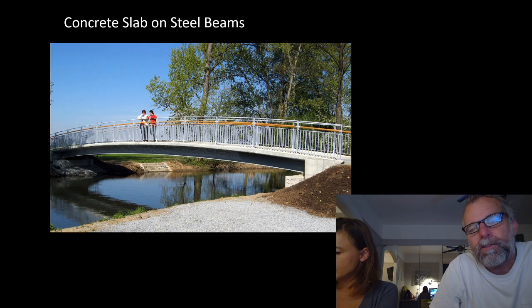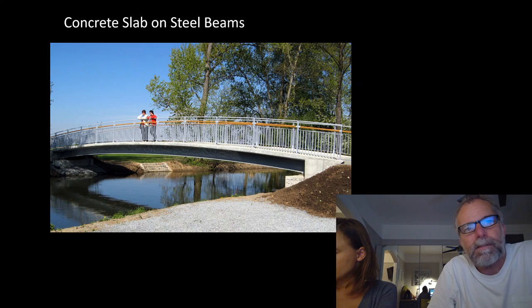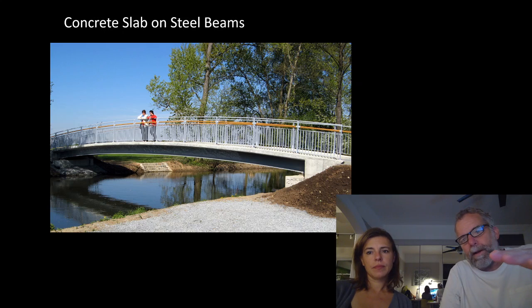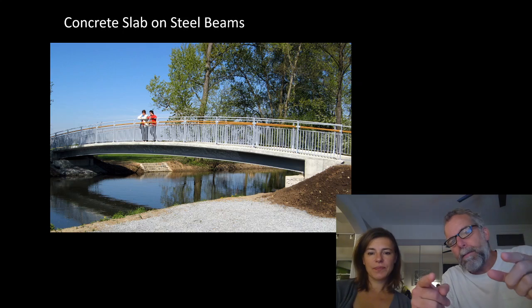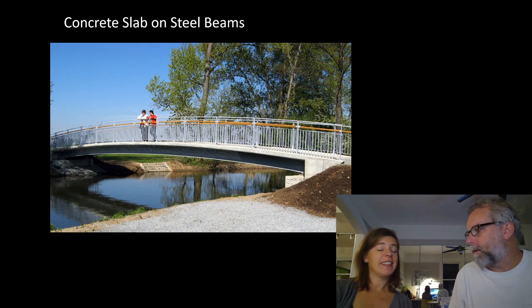So this is another nice shallow arch bridge, and again, it's an arch. It gains no benefit from being an arch, except that it provides sufficient clearance underneath for whatever vessel needs to get under it. You might ask, why not just lift the bridge and have it flat? Totally valid, but you have to get up to the bridge, and so simply lifting the bridge means that you've got a big, long approach, or ridiculous sets of stairs.